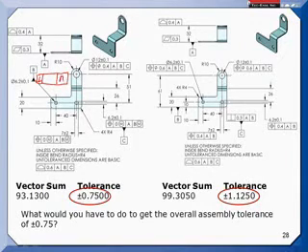In parts like this, sheet metal, when you punch a hole, first it rounds over, then you get a little bit of it, and then it kind of blows away, if you look at it in section. So only this portion right here is really hole B, feature B. I can't gather enough data on that to prove whether it is perpendicular or not.